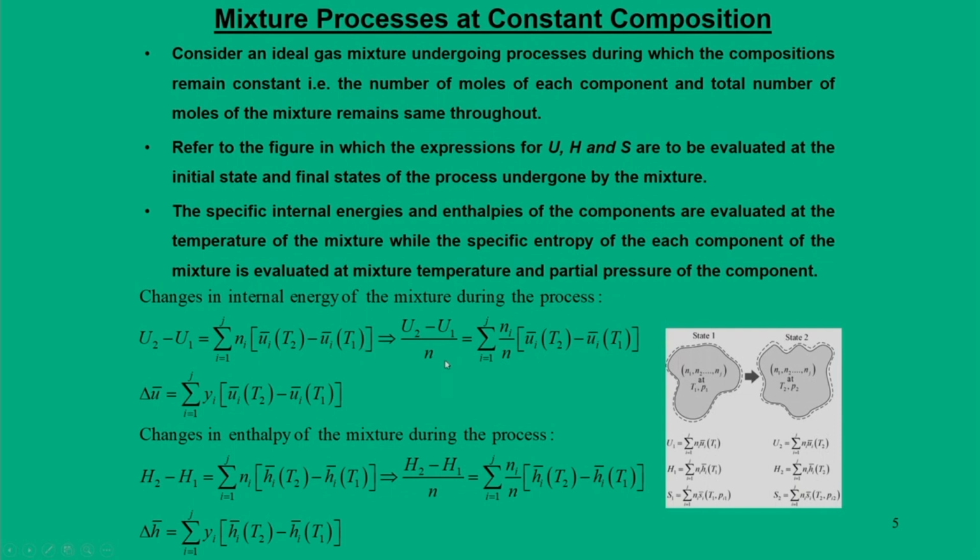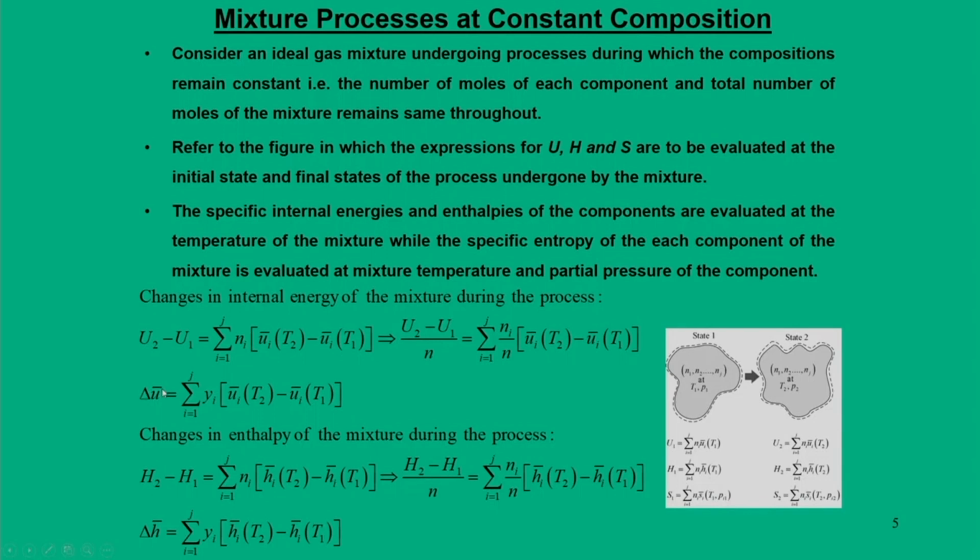By doing so, you can find the change in the molar specific internal energy, which is the summation over the internal energy change of each individual component i between state 2 and state 1, multiplied by its mole fraction. If you sum over all the components, we can calculate the total change in the molar specific internal energy. A similar philosophy can also be applied to calculate the change in the molar specific enthalpy.